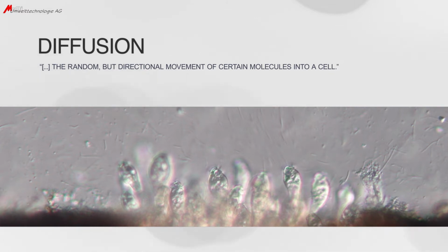The diffusion effect in biofilm processes has to be understood as the feed of substrate and oxygen molecules into the active biomass. Nutrients, like for example phosphorus as well as oxygen, diffuse from the surrounding water into the active biofilm and supply the microorganisms in the pores. In other words, diffusion is to be understood as the supply of the biofilm or the microorganisms on the carrier with substrate and oxygen. Substrate refers to the pollutants present in the water which are to be degraded by the microorganisms. A sufficient diffusion is an essential factor for the removal performance of active biomass.